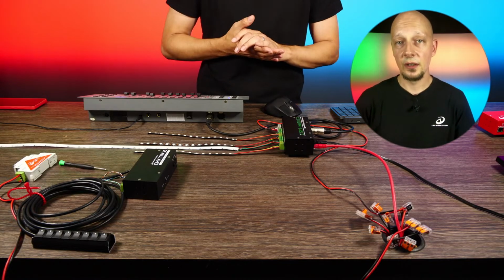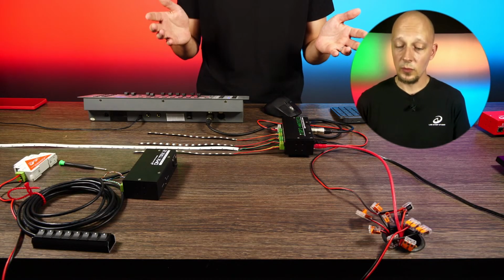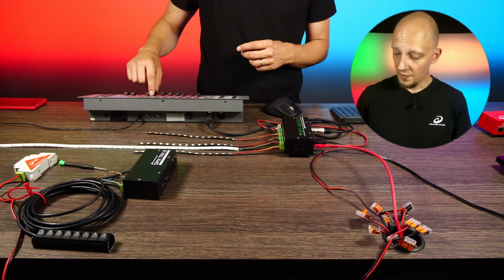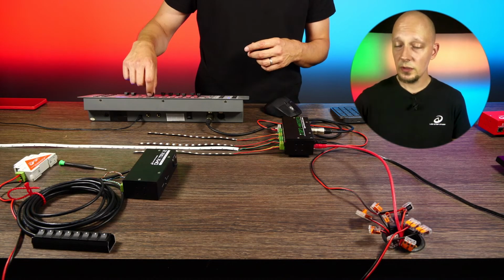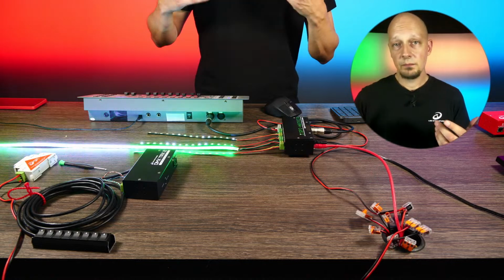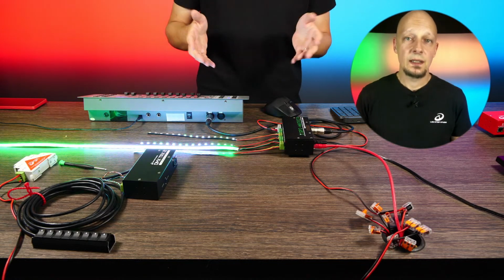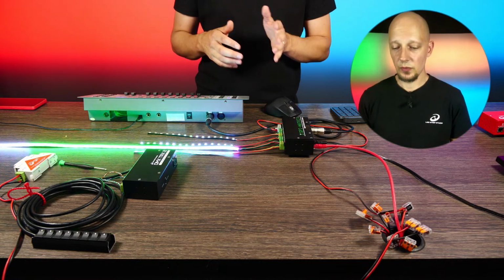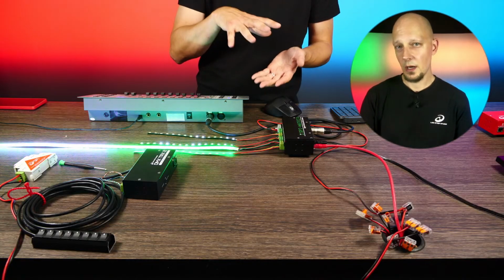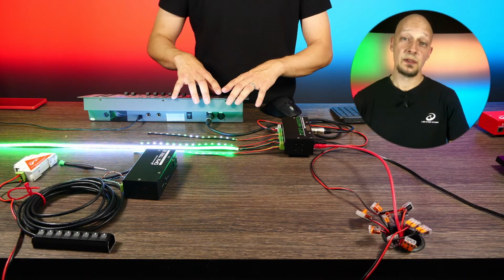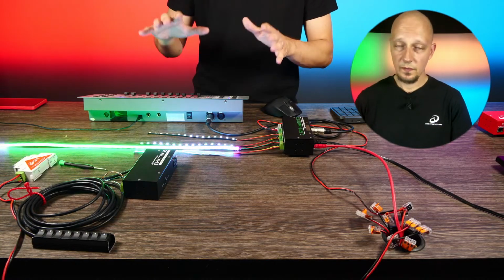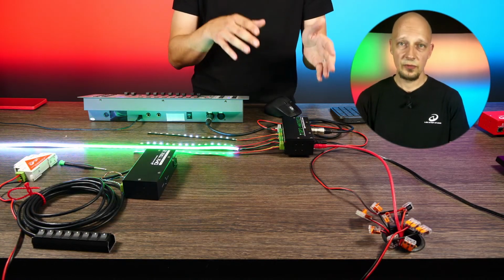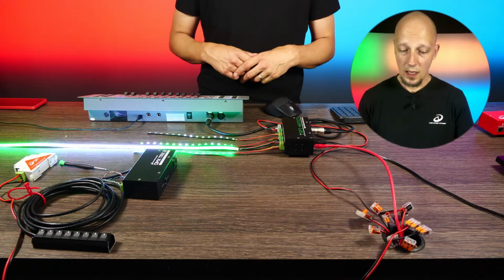I'm not using RGBW strips. I don't have a white LED inside, so the 7th channel is basically useless to me. But it would illustrate how you would use DMX to control the content from the card. So remember, you have to reserve 7 channels, then you can use DMX to trigger the effects from your device.